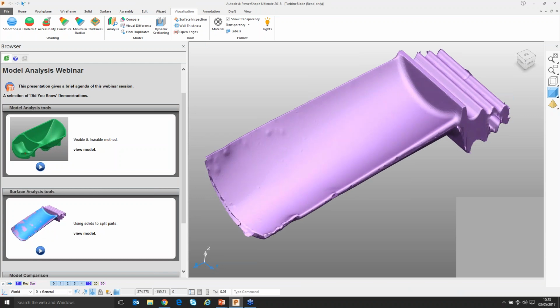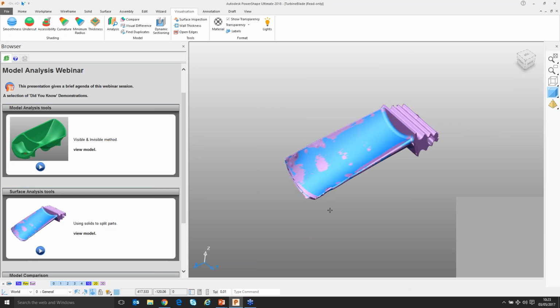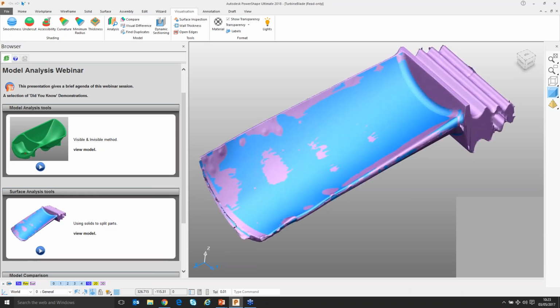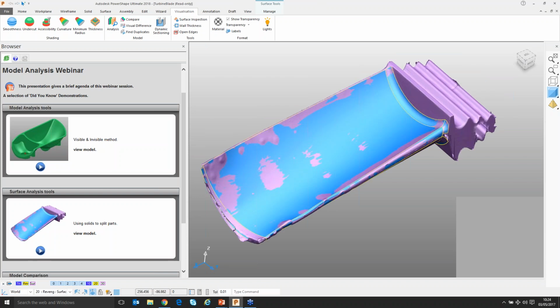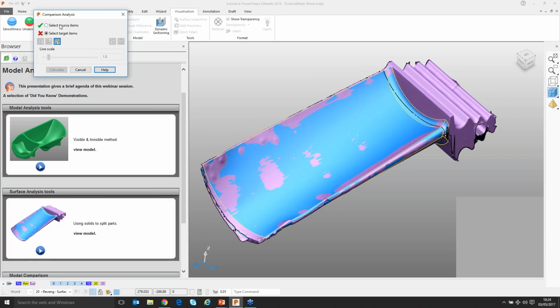just there. And what I'd like to do now is find out how good I was, how well I've matched one to the other. So if I box select all of this and deselect the triangles for a moment, I just have the surfaces selected. I can go to the analysis page. You can see that immediately it tells me, well, you've already got some source items selected. You don't have any target information selected yet. So hovering over this, the radio box is selected here. So all I need to do is click the triangles and I get a tick for both.